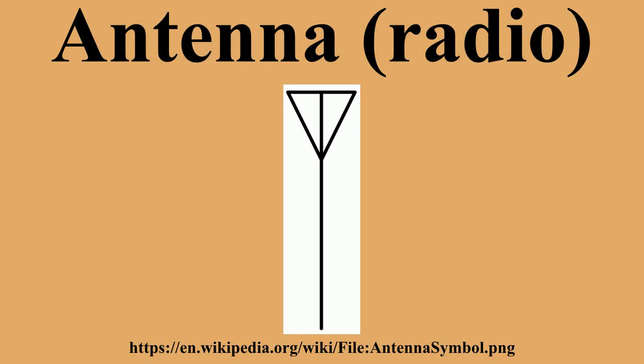The Yagi antenna has similar-looking parasitic dipole elements but which act differently due to the somewhat different lengths. There may be a number of so-called directors in front of the active element in the direction of propagation, and usually a single reflector on the opposite side of the active element. Greater directionality can be obtained using beam-forming techniques such as a parabolic reflector or a horn.